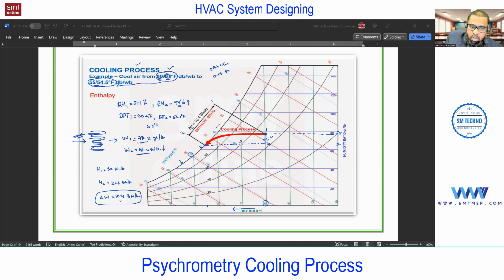Adding or removing moisture does not mean that the RH also increases or decreases in the same way. If you maintain the same temperature, yes. But at a different temperature, the RH level will be different. It does not mean that adding moisture must increase the RH level. No, that depends on the temperature. As the temperature increases, the moisture holding capacity of the air increases.